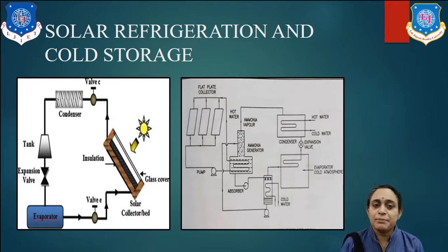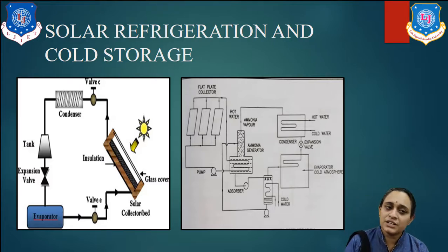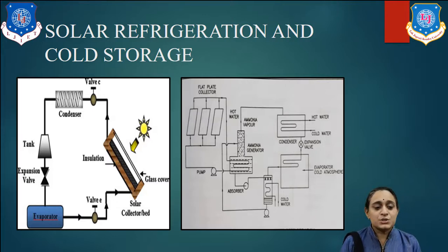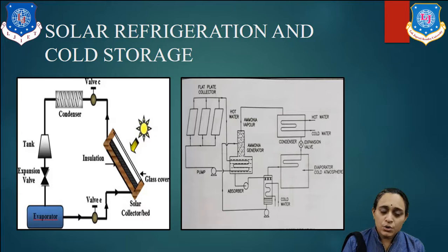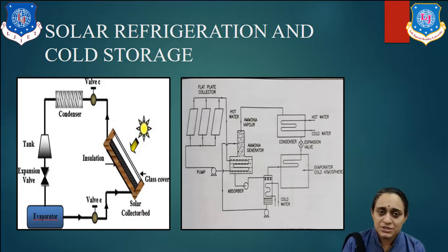The evaporated ammonia goes back to the absorber, where the cooling water absorbs the ammonia, and again the ammonia solution is prepared. So by using the generator, evaporator and condenser, we can easily get cooled air from the heated circulating water. This process is repeated in cold storage as well as refrigeration, and it depends upon proper refrigeration fundamentals. In our domestic purposes we use electricity to produce the cooling effect, just like air conditioning and refrigeration. In the same way, we can use the solar refrigeration system.